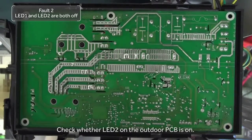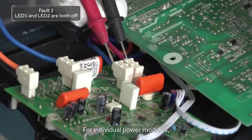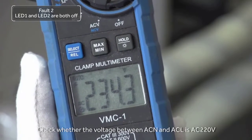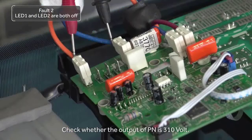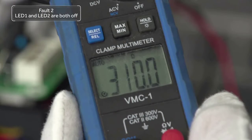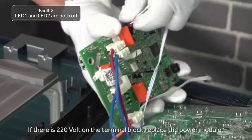Check whether LED 2 on the outdoor PCB is on. For individual power modules, check whether the voltage between ACN and ACL is AC 220 volt. Check whether the output of PN is 310 volt. If there is 220 volts on the terminal block, replace the power module.